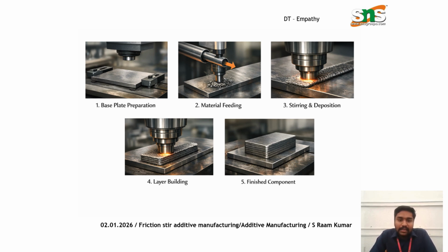After each base plate, the material will be fed at every structure with a layer height of 0.5 mm thickness at every layer. It can vary up to 1 mm. So the layers will be built at 0.5 mm from one layer to another. So it will be easy to overcome the post processing and removal structure.